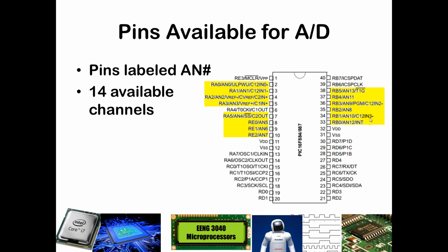So here are the pins that are utilized in the analog to digital conversion module. So anything that has an AN0, we talked about this early on in one of our first lectures. So AN0 is analog channel 0, AN1 is analog channel 1. Here is an interesting thing. This can actually be either your reference voltage, Vref minus, and this one being Vref plus if you wanted to determine your own analog to digital reference, or this can be another channel of analog 2 and analog 3. The choice is up to you. So you can use this particular pin in a variety of different ways.